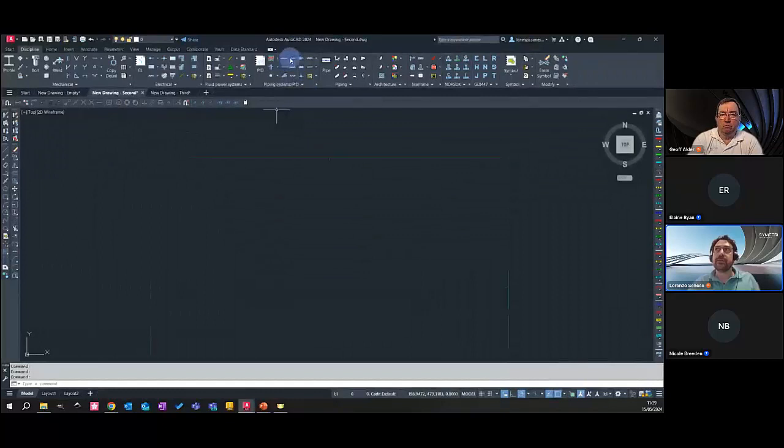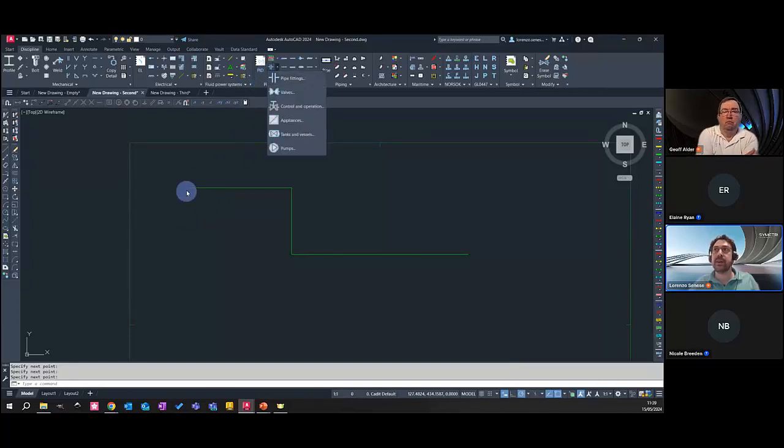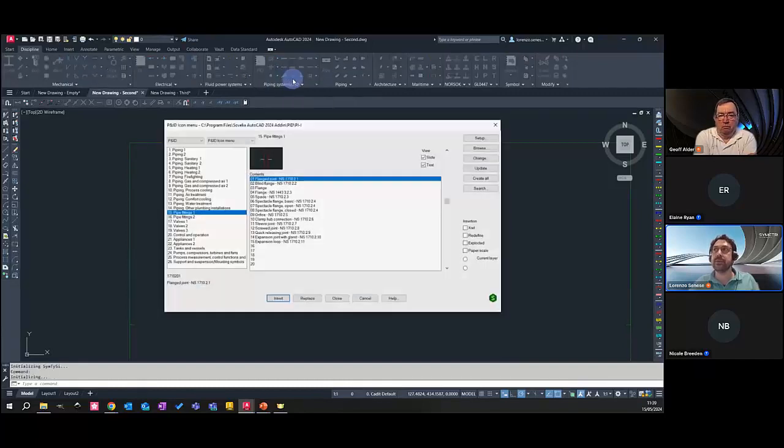Okay, I'm moving to the following example, and I will show you the P&ID section. For the P&ID, I have different types of piping, so for the purpose of this example, I'm going to draw a main piping line, like that. This is my main piping line, and I want to include the P&ID symbols. I'm adding a blind flange at the beginning and the end.